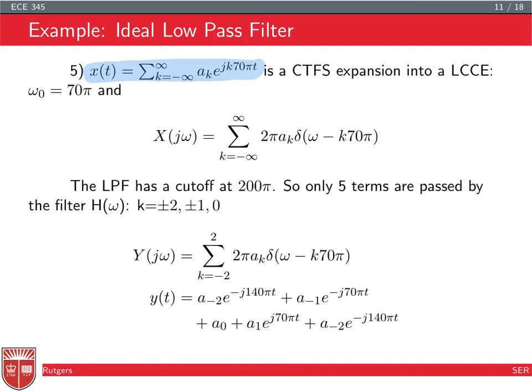Now, if you recall from what we studied maybe in the second lecture, in the frequency domain, the complex exponential e^{jω0t} is equal to 2π δ(ω minus ω0). Which makes sense, because e^{jω0t} is a cosine plus j sine, so these are one frequency at ω0. That's why you get a frequency at ω0.